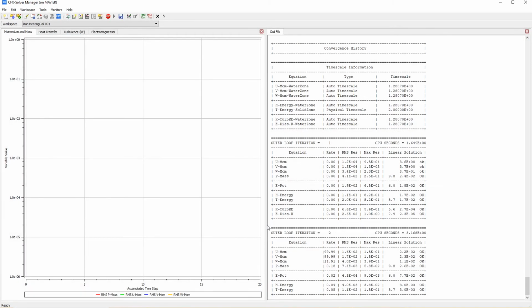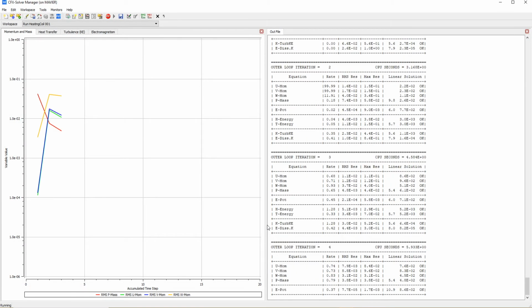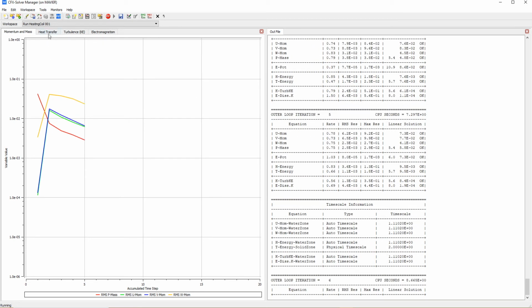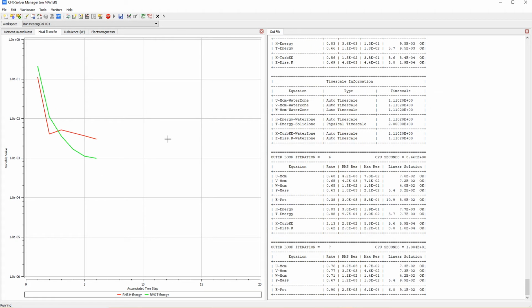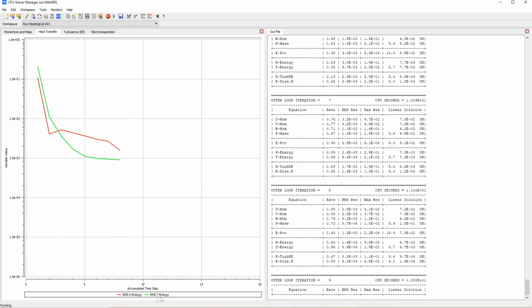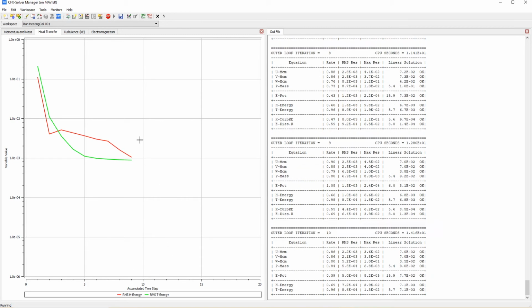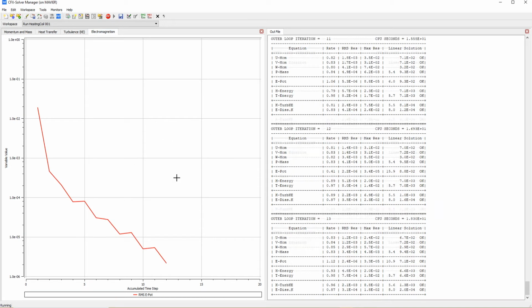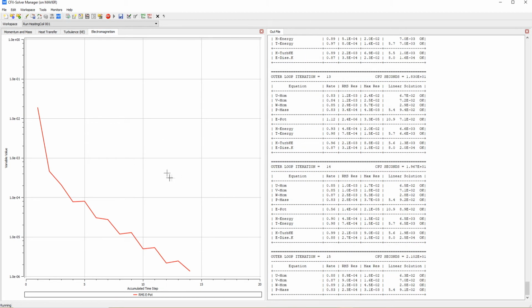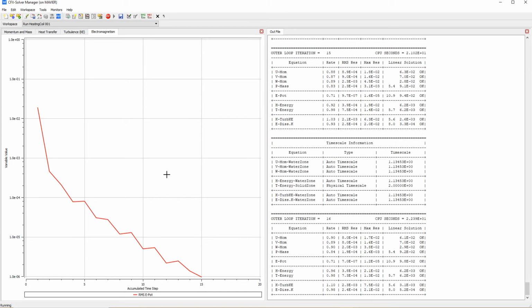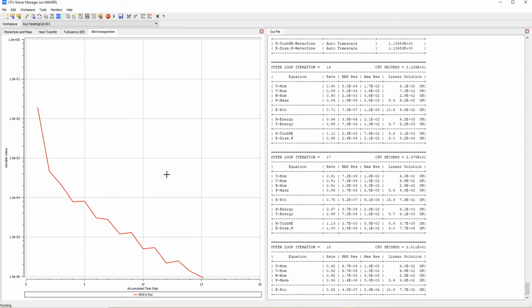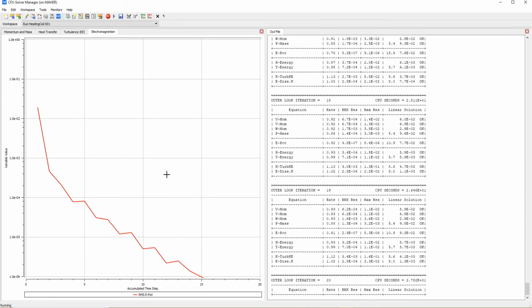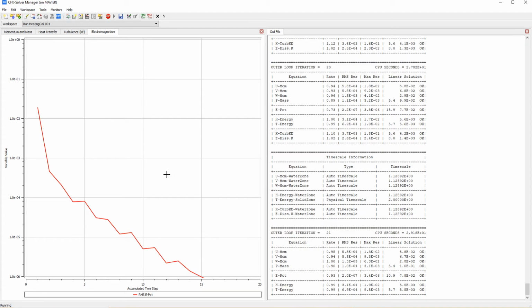What I want you guys to send me here is this window right here. You can see that we have the energy for the thermal energy here, but also we have this new tab, the electromagnetism tab, that we didn't have in our previous simulations because we were not working with electricity.